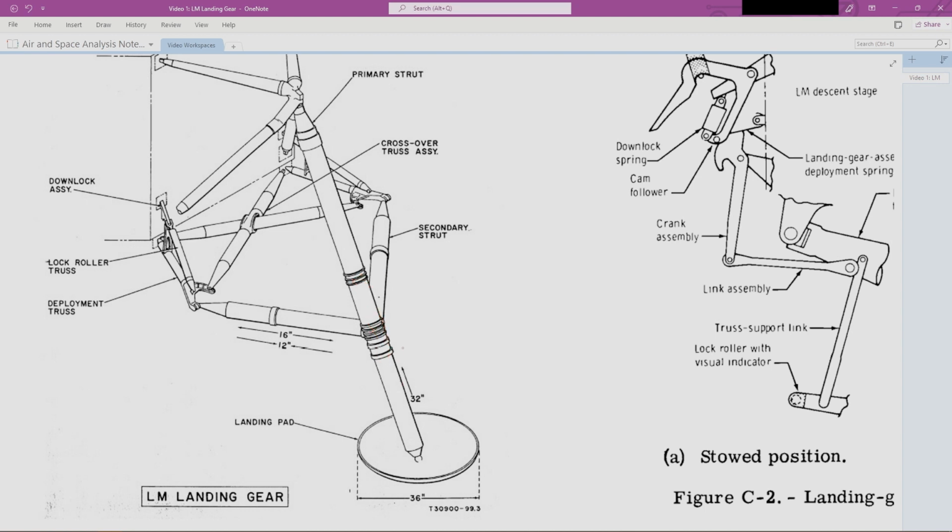So essentially it's literally a beehive structure, like a honeycomb of aluminum. There's just an actuator face in here that pushes on it, and at a certain force, determinable based on the density of the honeycomb, it'll start to crush. That can give you constant force in the structure, as well as a capped acceleration so as to not overstress the lunar module as it's coming in for a landing.